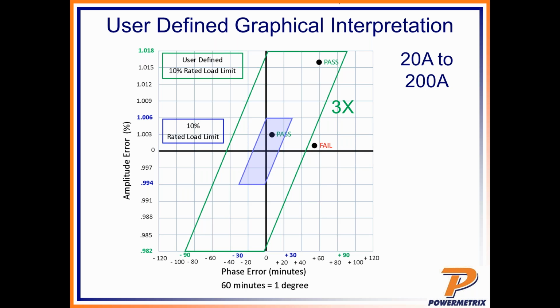So yeah, if you have to use probes on both the primary and the secondary current, the calculations and what the PowerMaster does is the exact same thing. You're just going to have more possible error introduced into that measurement by the 2 sets of probes. Meaning if that happens, you might even have to take your user-defined multiplier and make it a little bit bigger in that case, just so you're not saying failure all the time, okay?